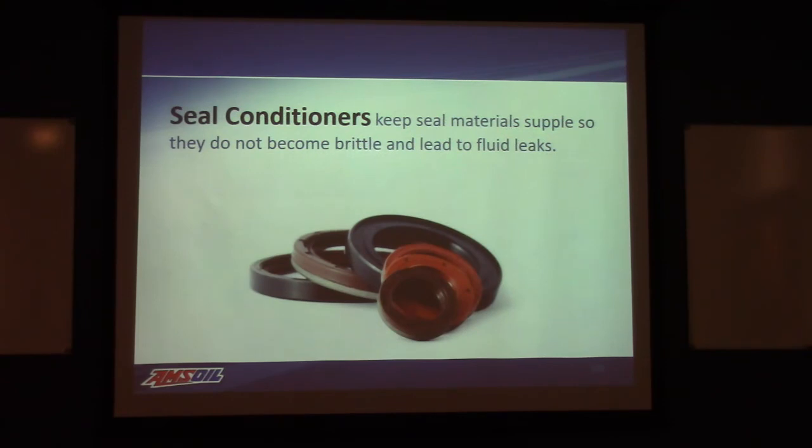But how about if it balloons it up and makes it real soft? So now it wears at a higher rate. That would not be any good at all. Or what happens if it negatively reacts with the seal and causes it to become brittle? Now it could crack or wear at a higher rate. You want to make sure that whatever oil is being formulated, that the chemistry and the base materials are such that they have perfect compatibility with the type of elastomers, the seals, the O-rings, that type of thing that are in the application.